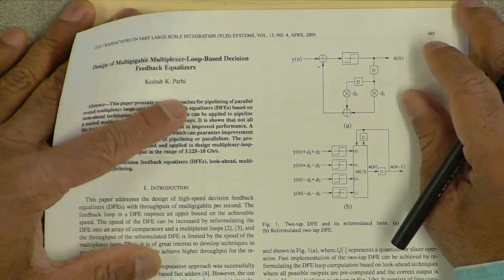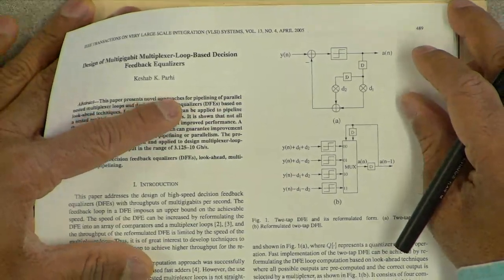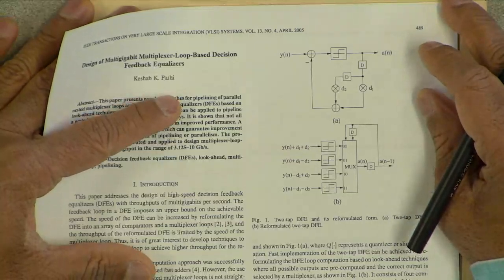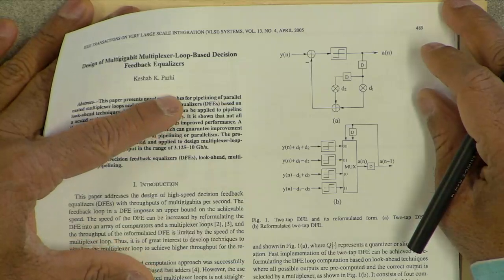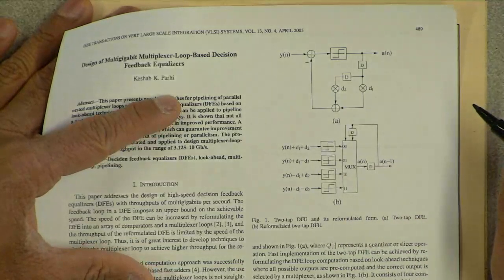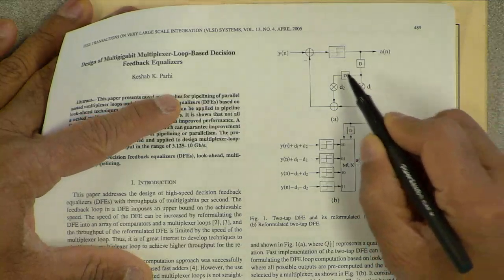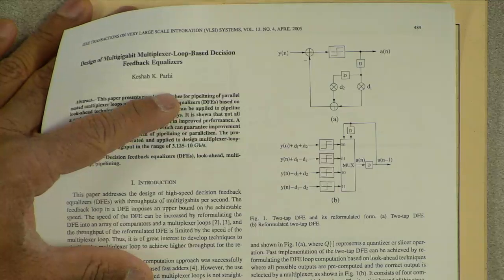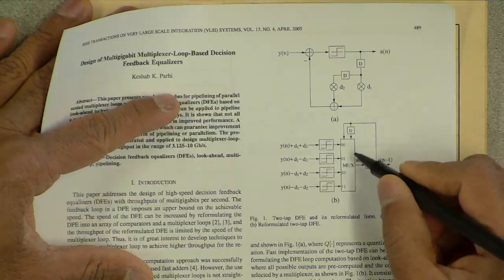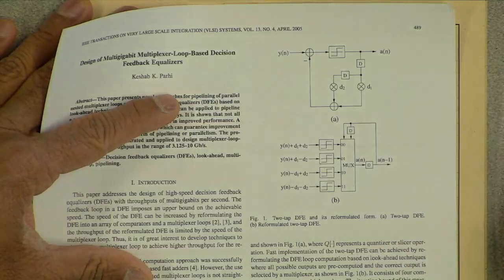And it turns out that the optical fibers are always running at tens of gigabits per second, all the way to 400 gigabits per second, and it is really very hard to operate. So this is the same example from the previous 1991 paper, that if we had a 2-tap DFE with a 2-level decision device, I could pre-compute these 4 things, and then we just have the 4 to 2 multiplexer as part of the feedback loop.